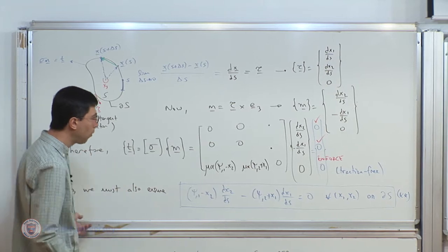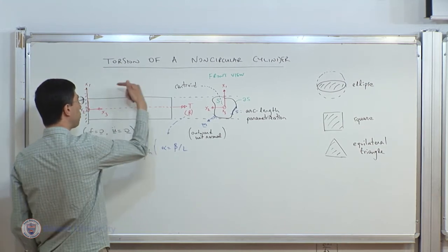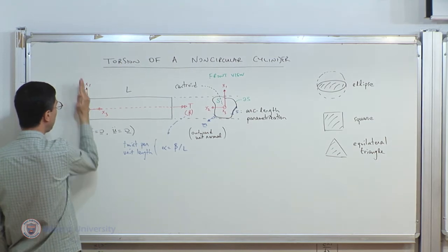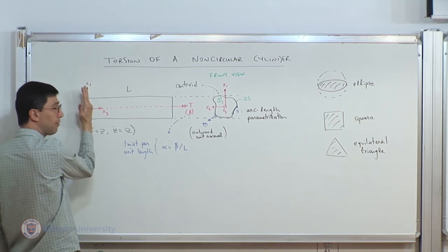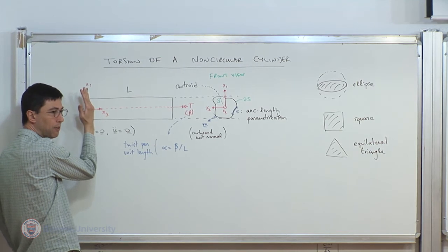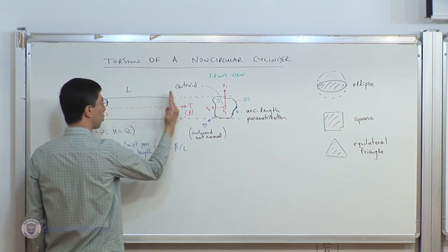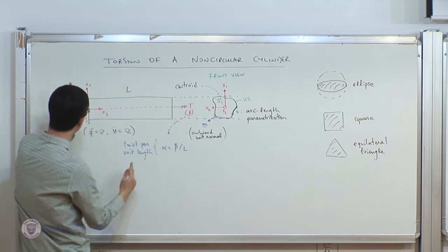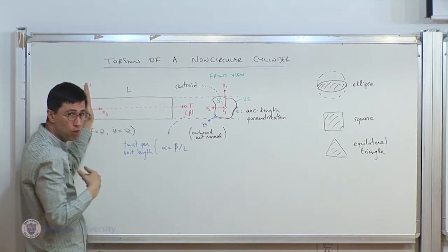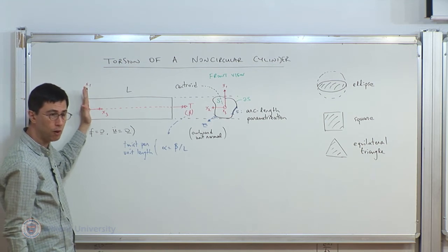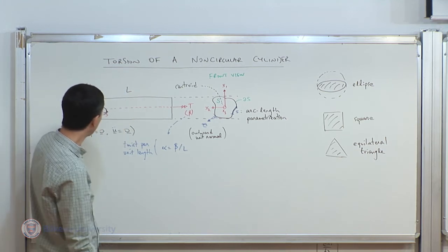So now that we have the major things, let's get the minor things out of the way. We took care of the boundary conditions on the lateral surfaces. Now, the boundary condition here, I will postpone it. It's not a big deal, really, because it will eventually come in through our solution as an end effect. So when I do a comparison with the numerical solution, now remember, there's a warping, which says that every cross-section will have also a displacement in the x3 direction. When I fix everything on this end, it cannot possibly get displaced in the x3 direction, and therefore the cross-section cannot warp at x3 equals 0. But that's going to be an end effect. It's going to exponentially decay towards the warped solution, okay? So this part I'm not going to worry about.